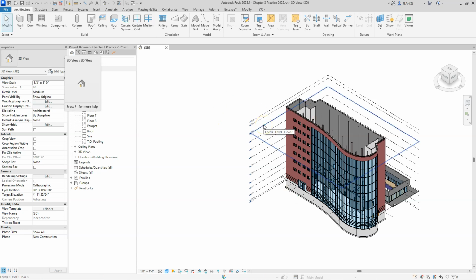As you're doing that, we're going to be talking about views today. And views, you'll recall, are all listed in the project browser. So everything in this window right here, most of these things are views. Certainly the things at the top listed are views, and it starts off with floor plan views, and you can see that this particular drawing also has ceiling views, 3D views, and elevation views. We don't see any section or detail views in there yet. None have been created, but presumably if we do create something like that, it's just going to automatically add that to our project browser.